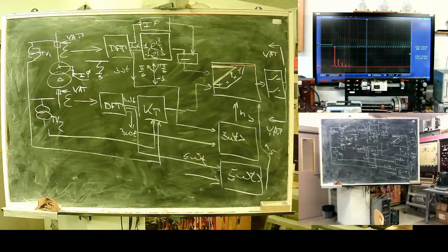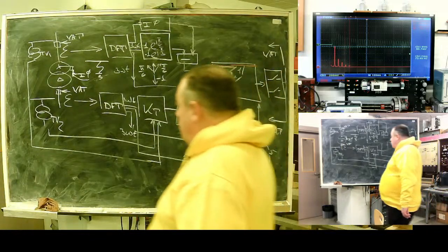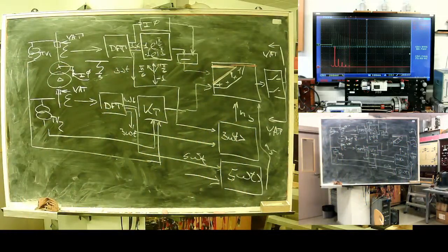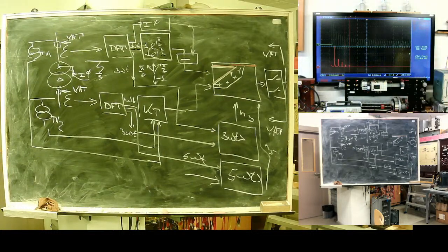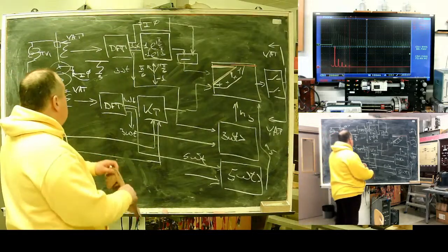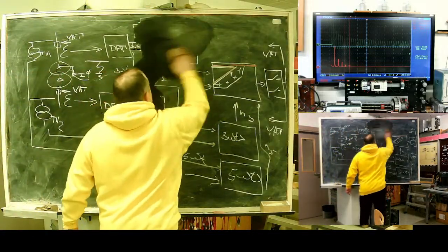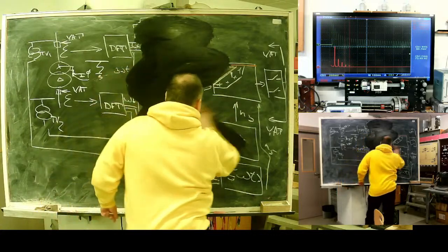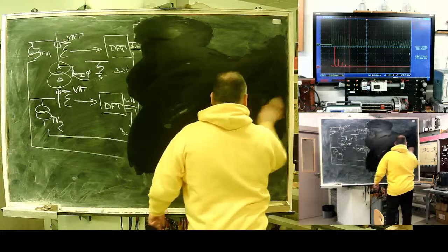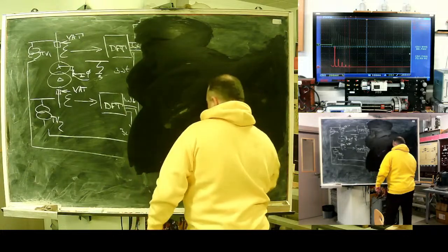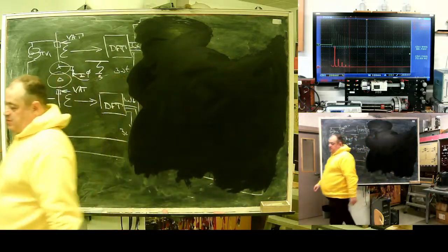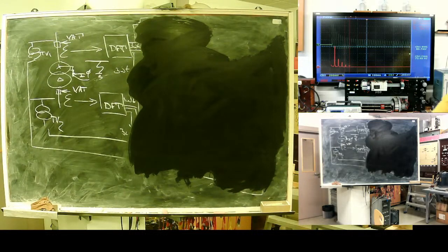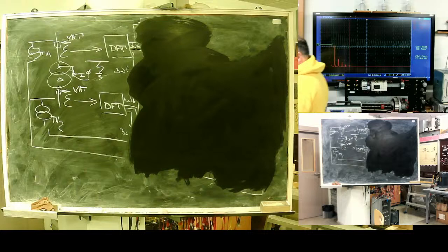To increase sensitivity, one more operation branch can be added to increase sensitivity. I will erase part of my scheme. Another operational branch can be added, and this branch is a negative sequence differential protection.